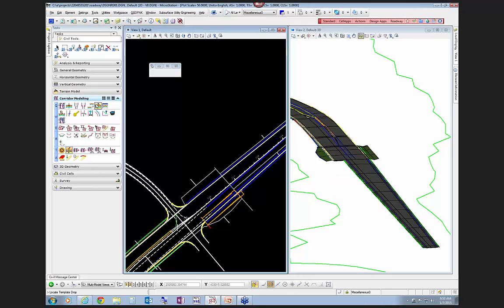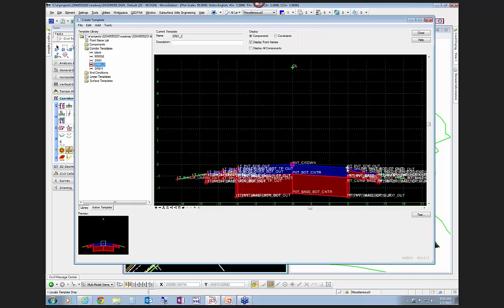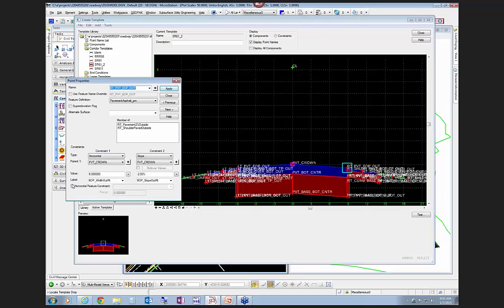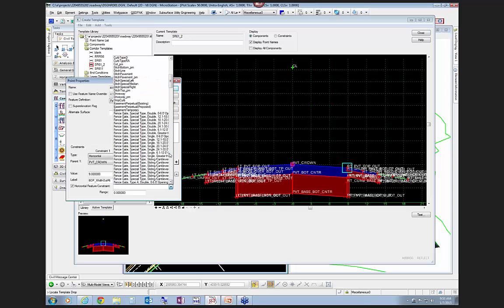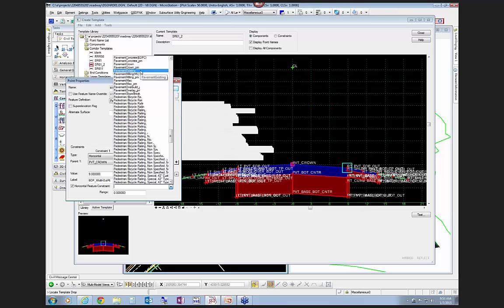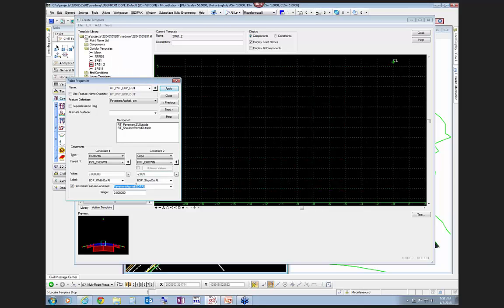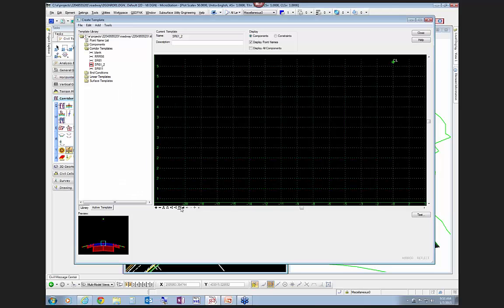Now, believe it or not, if you just sometimes check it back on and go pick the horizontal feature that you're trying to target, this pavement asphalt, and set the range again to 50 feet. And just to make sure it's different, I'm going to set it to 55, choose apply, and make sure that that's set again.